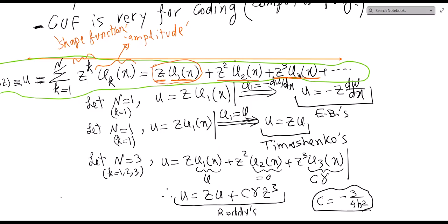So these two are warping. This one and this one are related to the warping. Any theory that truncates here assumes plane remains plane. But how do we know? Maybe plane doesn't remain plane, and these two terms come in. These are warping, and the rest of them.